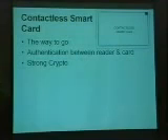Contactless smart cards. In my view, the way to go. They tend to have decent crypto. They authenticate the reader. If you have a standard prox card reader, it will read pretty much anyone's prox card of that frequency, so you can stand behind them in the street and read the data off their card. With contactless smart cards, there's at least some authentication, so you can't do that. There's a bit of a problem with them, and we'll get into that in a minute.